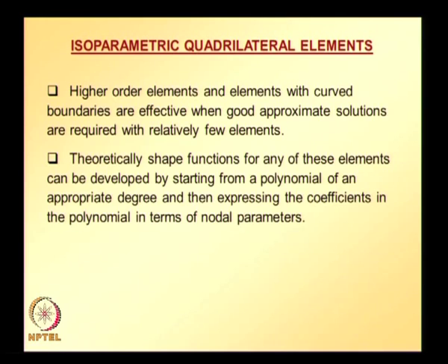Theoretically, shape functions for any of these elements can be developed by starting from a polynomial of appropriate degree and then expressing the coefficients in the polynomial in terms of nodal parameters or the nodal values, similar to the way we did for 1-dimensional elements, both 2 node elements and 3 node elements.